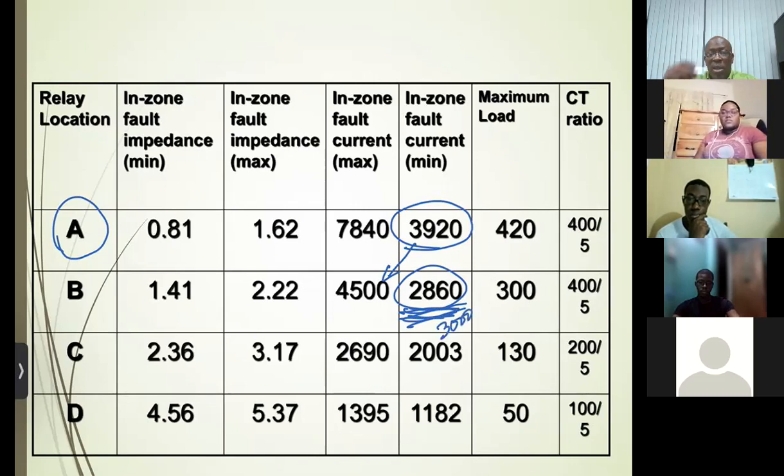Yes? Question, would that 3000 amperes be passing through A? Yes, sir. But A's minimum fault is 3920. So it wouldn't have been providing much help to B. Because it hasn't even seen its minimum fault yet. So, big deal. B is the one you're sweating, but who cares?